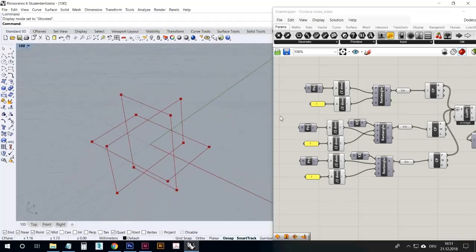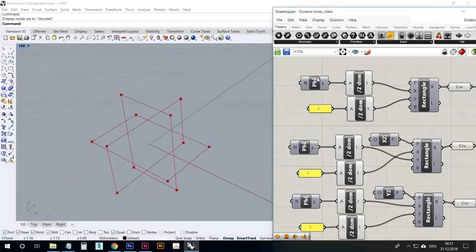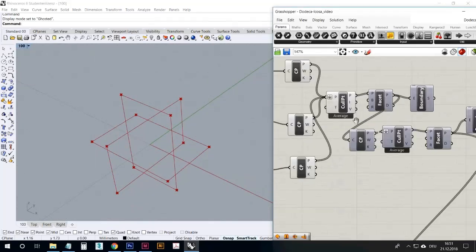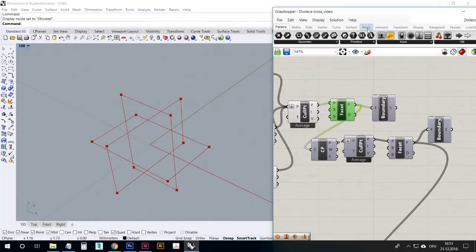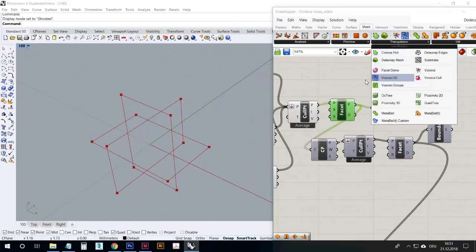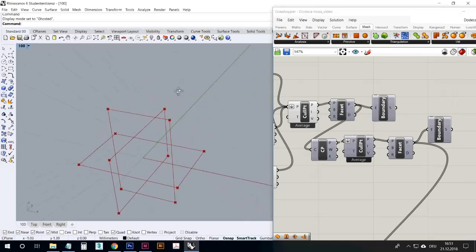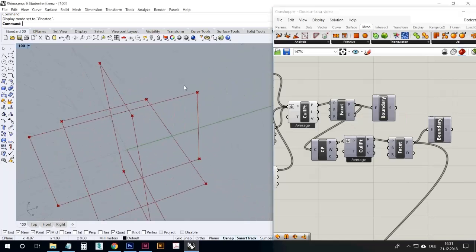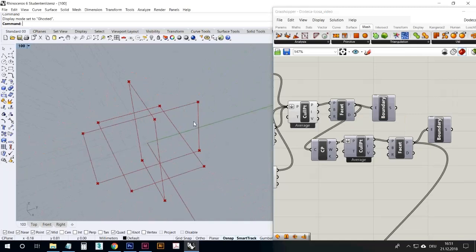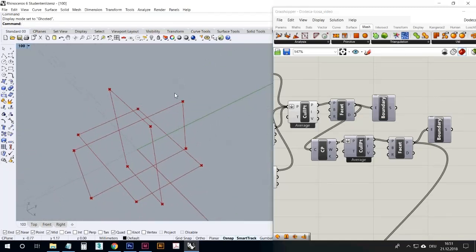We're going to build this from scratch soon. So here you see the constant phi, which is the golden ratio, which then goes into facets, which you can find on a mesh, and facet dome, which is a little script that makes a facet directly on top of a point, so to say. From a point collection, it draws a wall until the next point comes and makes a flat polyline.